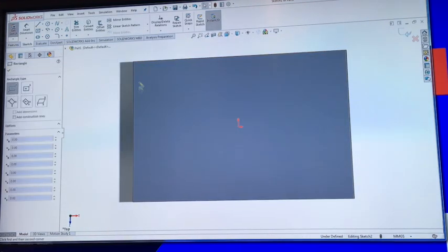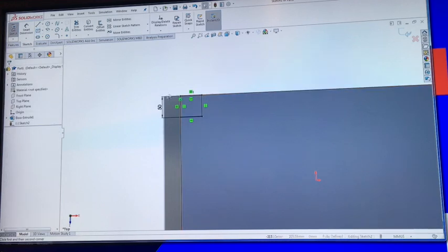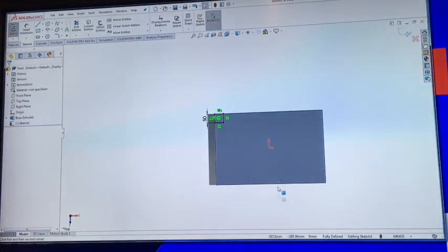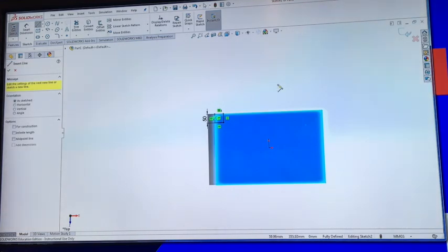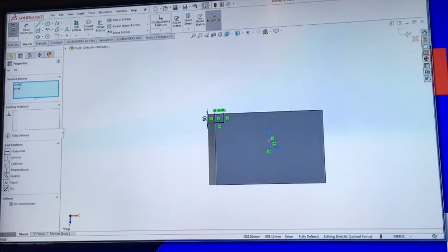What it means is when I create a shape, I've got dimensions automatically there, and I can just type them in, 50, and press tab to swap between them. All right, that adds the dimension, it even adds the equal relation for them as well. So instead of having to then go grab the dimension tool and add these relations, it does it automatically. I'm going to mirror that one around.